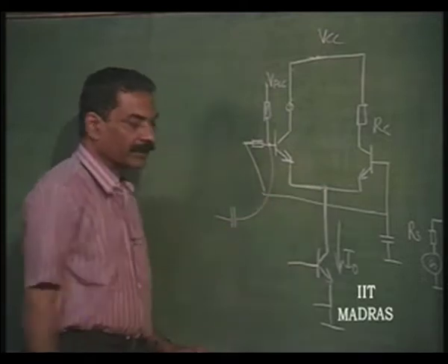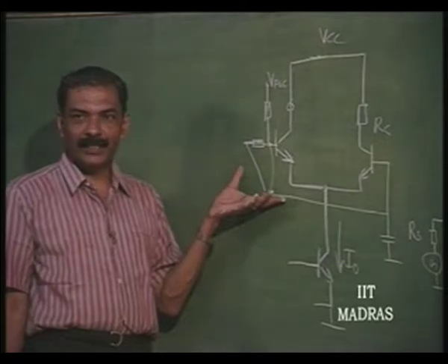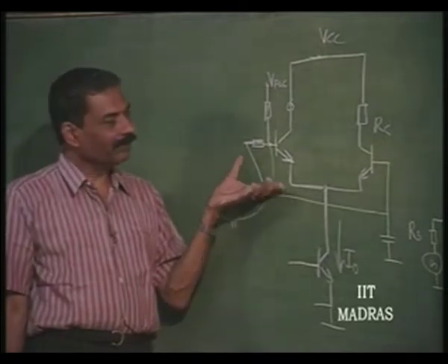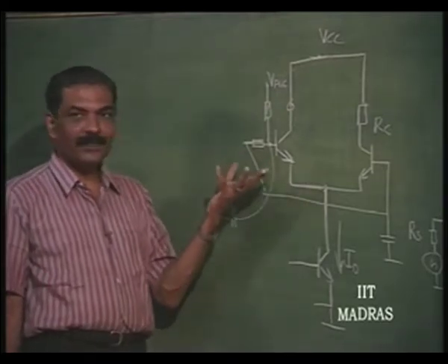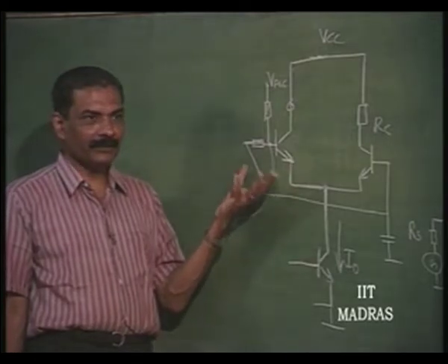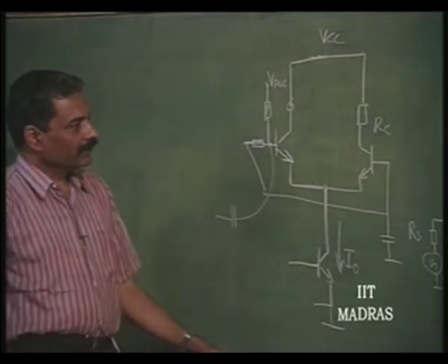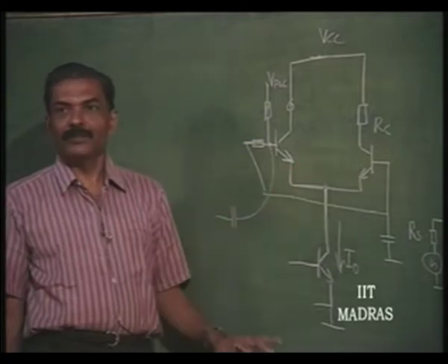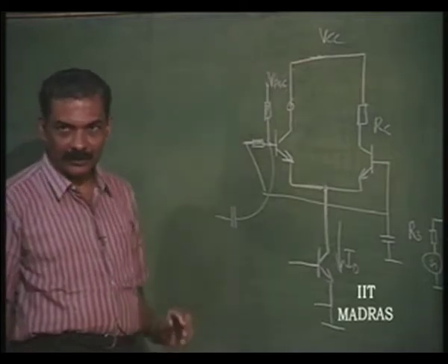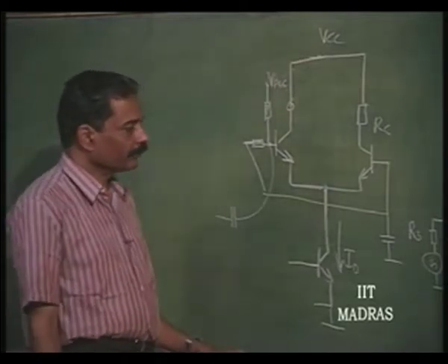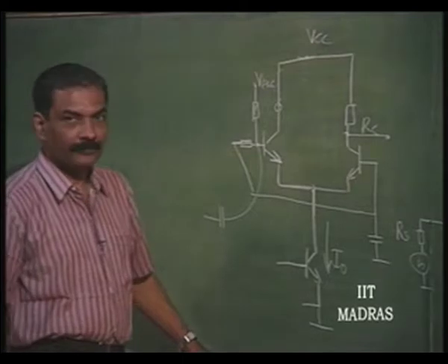So this is another wideband structure which can be used, but this does not have that disadvantage of AGC etc. and Y parameters not varying etc. Y parameters will vary as I naught varies. Therefore, if it is a fixed frequency amplifier without a requirement of AGC, this stage can be used, a wideband structure for tuned amplifiers, or it can be straight away used for a video amplifier where you do not apply the AGC. This AGC terminal is not used, so you do not connect anything there. So this is one way of using this as a video amplifier.